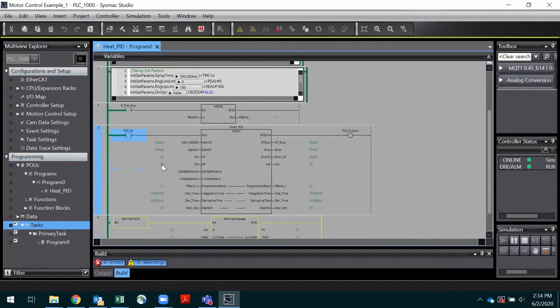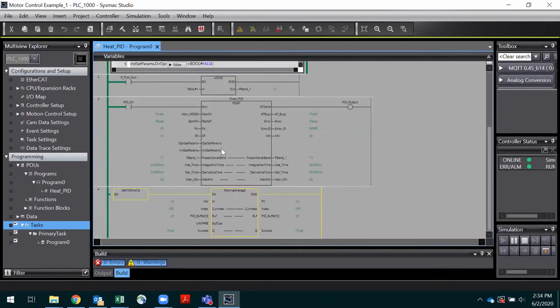Okay, so give it a set point. You won't be able to write anything to the PV now because it's being overwritten by that floating average. So you can write a set point of say 50, give it 1 second on the 2 time tuning variables, and then start the block up. Perfect. Now do an auto tune. There we go. It's still a bit jumpy.